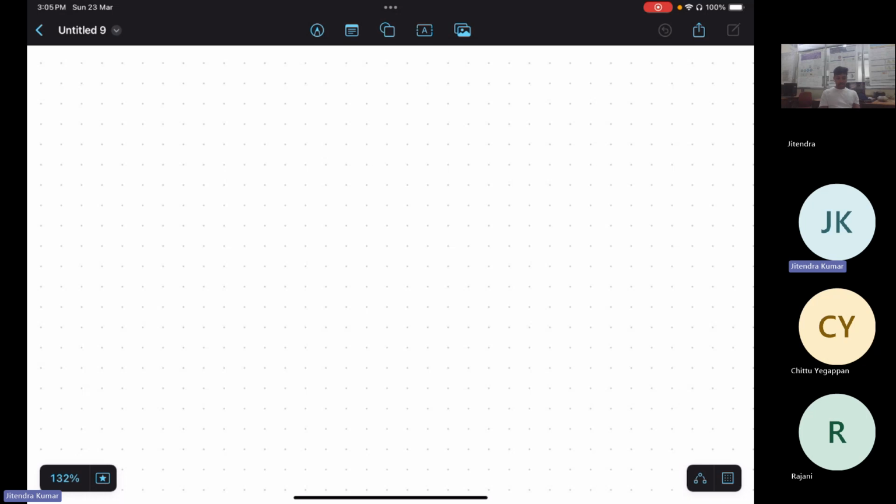Other than that, from drive circuit, you could observe that there is significant difference between these two motors. You need to supply different kind of supply to run switched reluctance motor. You need to do continuous switching. When your rotor starts rotating, once it is aligned with one tooth, then you have to switch off from the stator, then you have to switch on the next tooth, so that your rotor tooth should be aligned to the next tooth, so that force can be created and it should maintain its rotation. Okay.